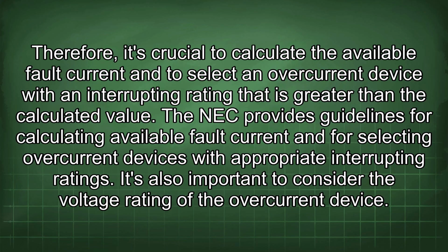Therefore, it's crucial to calculate the available fault current and to select an overcurrent device with an interrupting rating that is greater than the calculated value. The NEC provides guidelines for calculating available fault current and for selecting overcurrent devices with appropriate interrupting ratings.